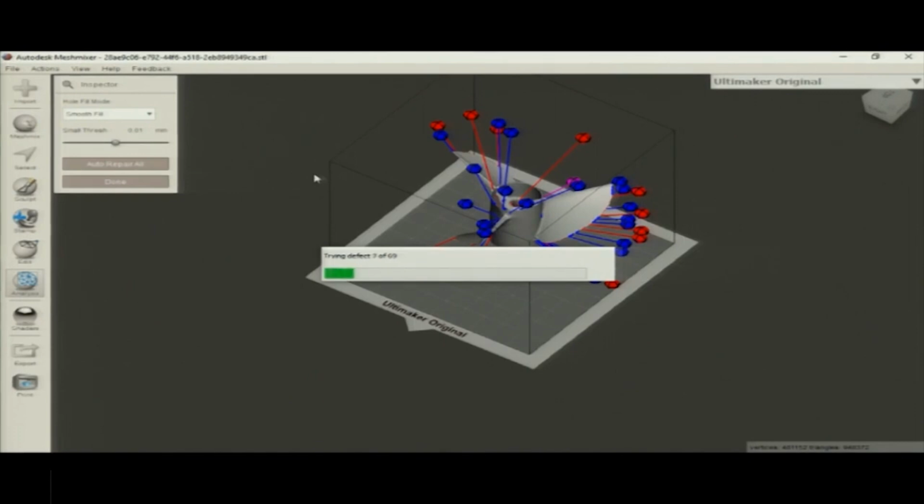It has around 69 defects, exactly 69 defects it is showing. It is repairing those defects. If we define the component on our own, these defects would not come. So, this is important when we do reverse engineering, to repair the defects or the voids that are there. These are the small meshes or small groups of nodes which are not selected properly while scanning.